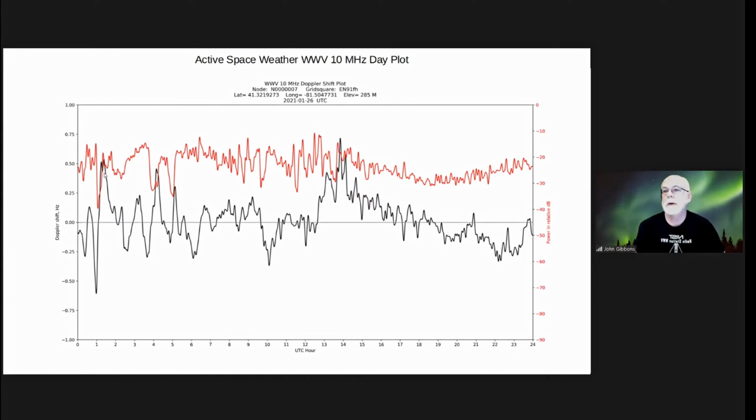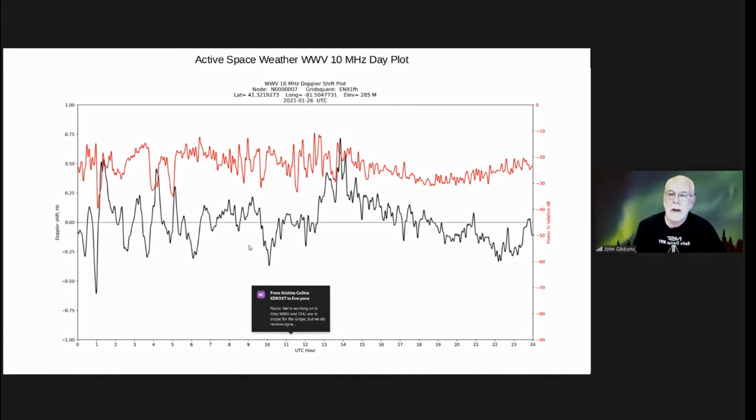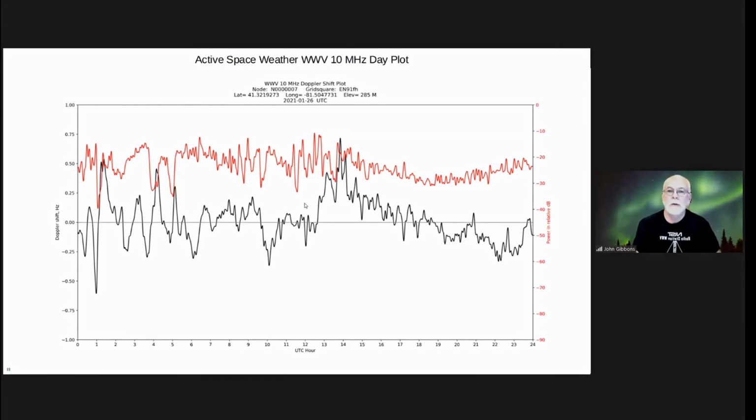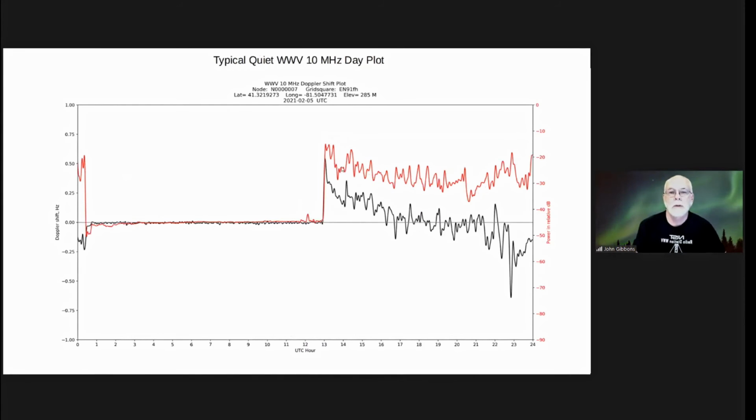But you see during the night hours, there's enough activity going on in the ionosphere. They're actually getting a very strong signal coming through, and you can see the perturbations of the offset of frequency as it goes along during the evening. So 2.5 and 5 megahertz are nighttime bands that we hear here in Cleveland, Ohio, and 10 megahertz is the daytime band. Again, showing this, we see this is basically daytime for Cleveland and nighttime for Cleveland.